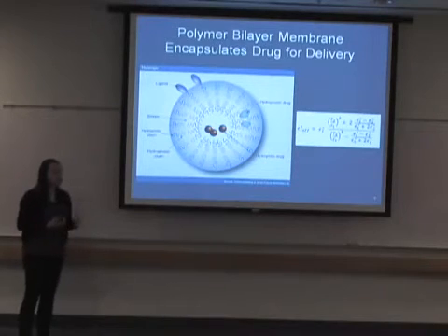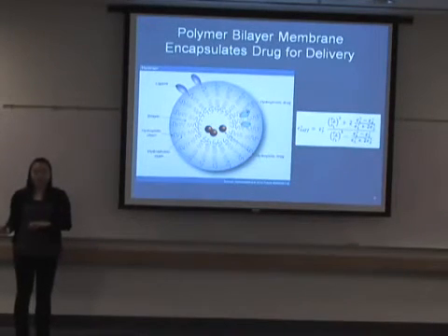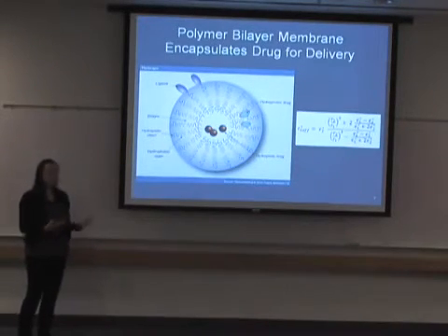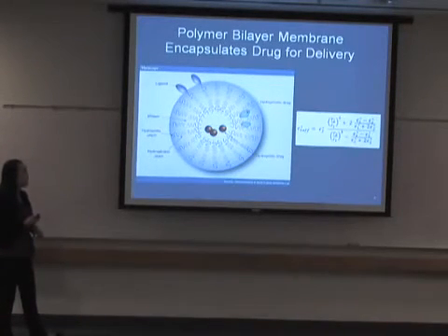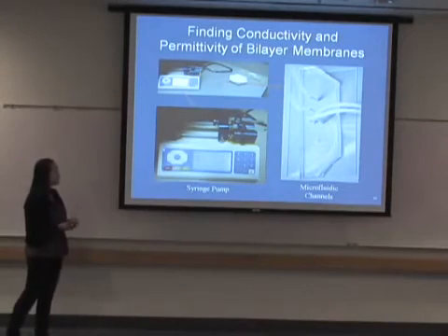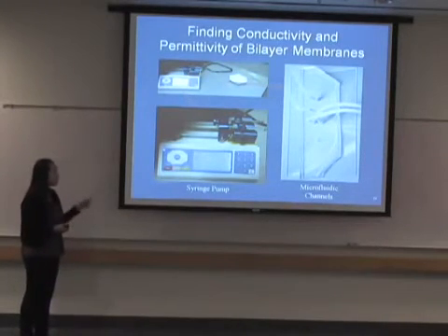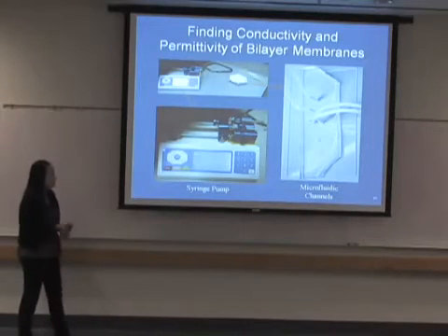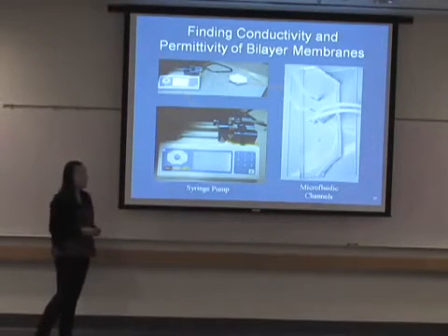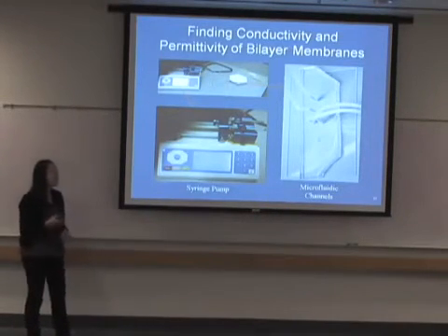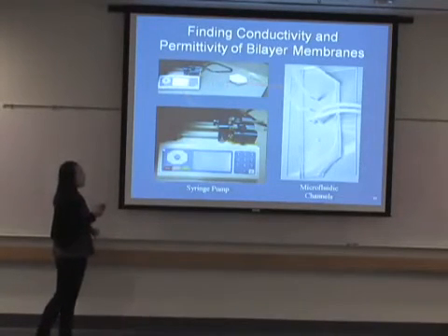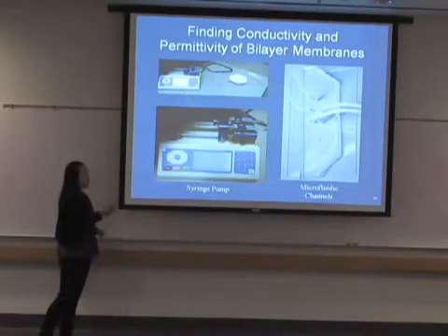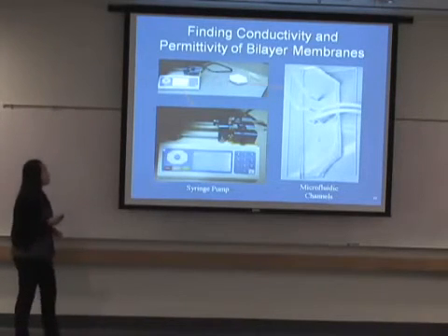We want to be able to conduct experiments in the lab and match them up with our simulations and hopefully get similar results. And so the way to do that is to do testing with microfluidic channels. So this is our setup. We have a syringe pump that automates how fast fluid is entering our channels, and 2 syringes. One syringe has our lipid solution, and the other syringe has our aqueous solution. And these fluids enter through tygon tubing that's connected to our microfluidic channels.